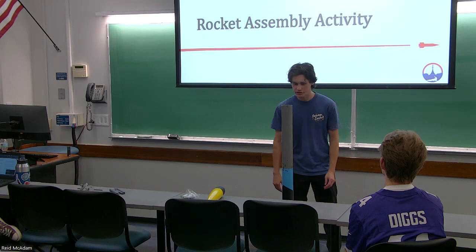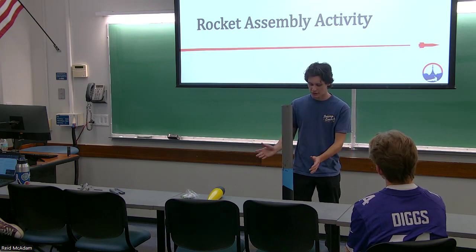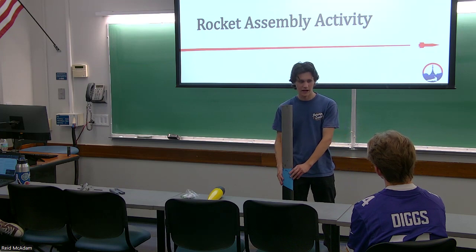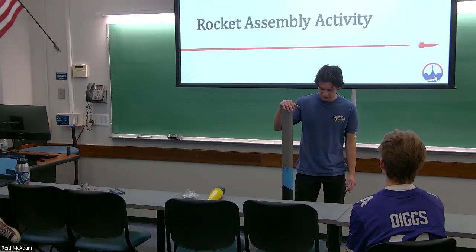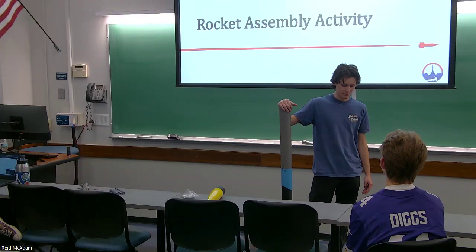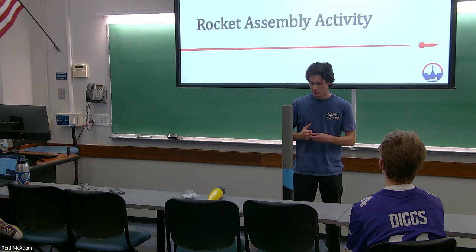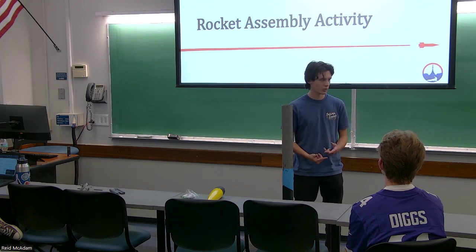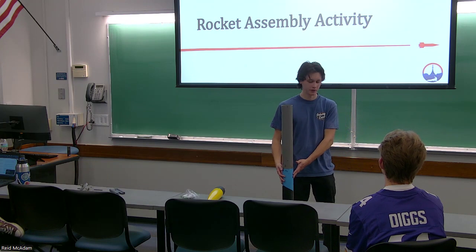So usually you'll have your main parachute in your forward section, and then you'll have your drogue parachute in your aft section, at least with a dual deploy rocket. The reason for this is because generally your aft section is the sturdiest. It's like we've got a bunch of epoxy here. And overall, it's got centering rings, it's more reinforced to handle the launch forces. So generally, we want this to hit the ground first and take away some of the energy.